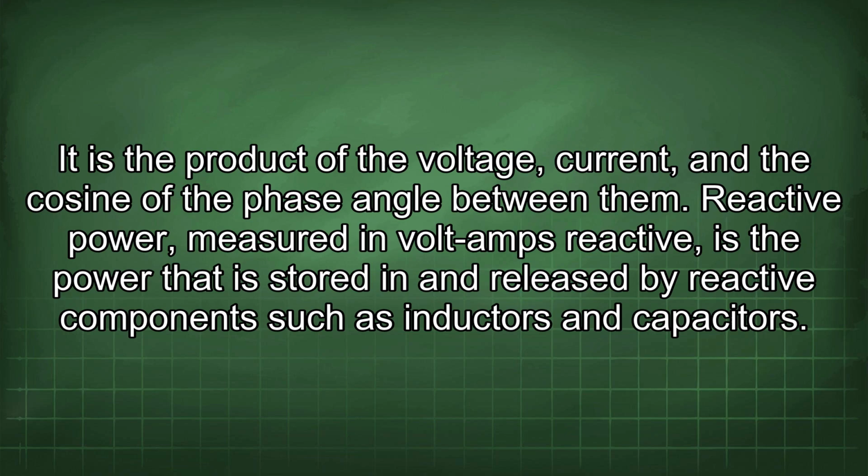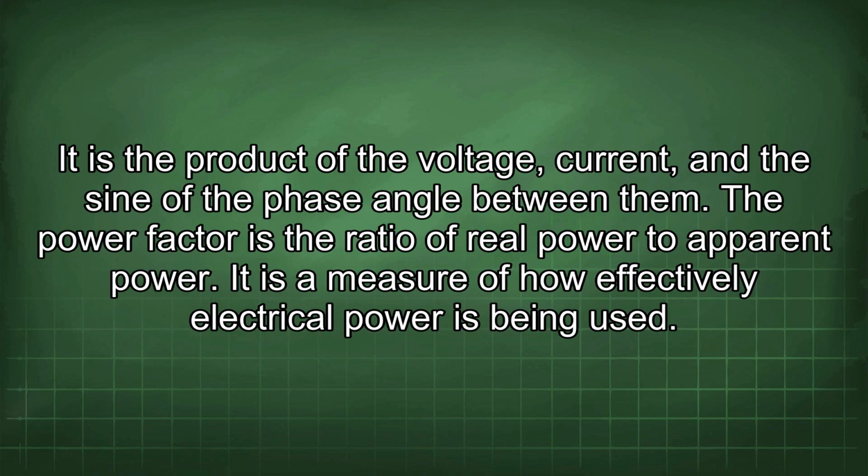Reactive power, measured in volt-amps reactive, is the power that is stored in and released by reactive components such as inductors and capacitors. It is the product of the voltage, current, and the sine of the phase angle between them. The power factor is the ratio of real power to apparent power. It is a measure of how effectively electrical power is being used.